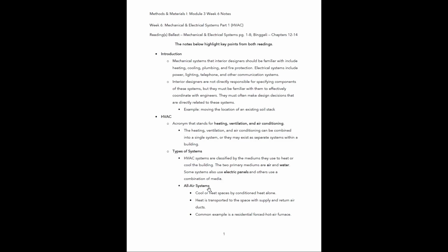An all-air system, so these are systems that cool or heat spaces by conditioned air alone. Heat is transported to the space with supply and return air ducts. And a common example of this is a residential forced hot air furnace.